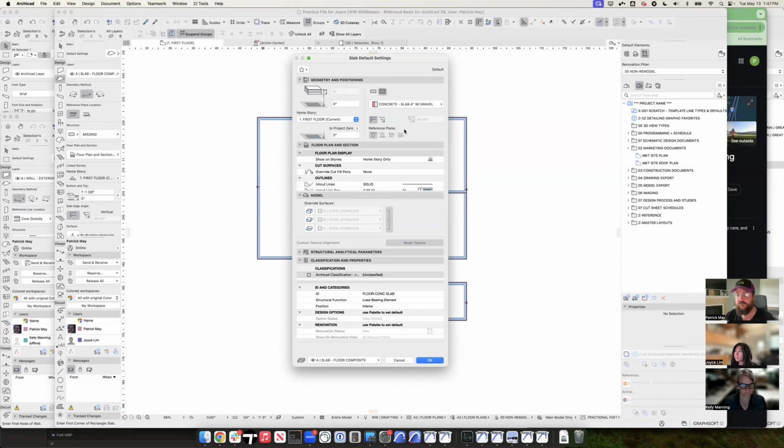We're always going to make sure that we're designing. In fact, a lot of times our framing plans get really complicated. And our concrete plans, we've even done slab plans to have 1/2 inch drops in the slab in order to accommodate different finished floor materials. So we're designing to the finished floor. And then same with the ceilings. If it's a ceiling, we would put the reference plane at the bottom of the ceiling slab. So we're really talking about the finish height of that space.